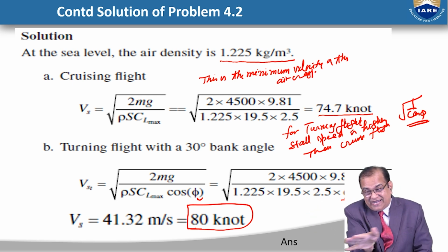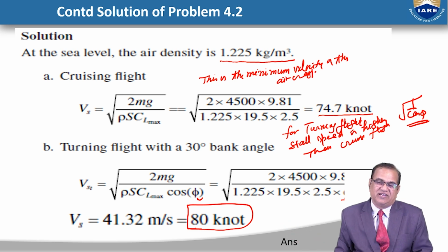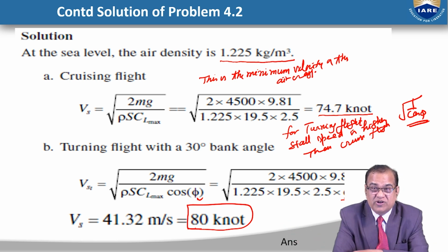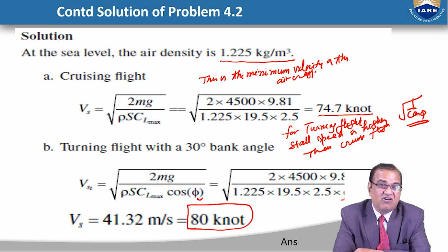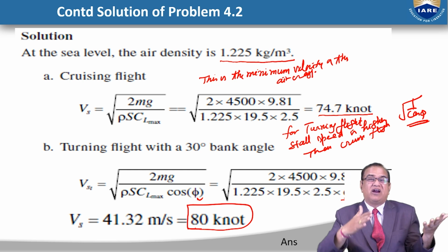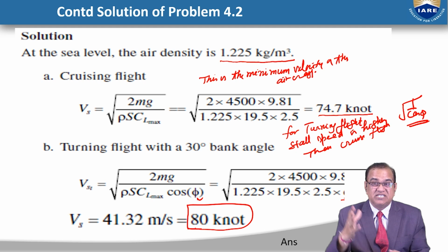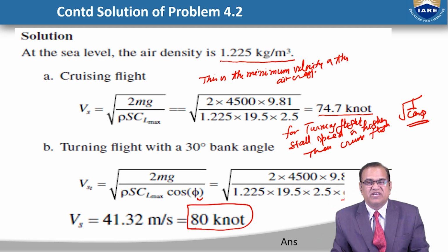If it is a high bank, your velocity will be higher and higher. So we cannot go like 90 degrees. We have to go some angle for the turning. These all things we have to decide before attempting the design. We are all engineers, and we should not just start. First we understand that our aircraft will turn and how much maximum turn is possible by this aircraft. This you can calculate by using this type of equations.